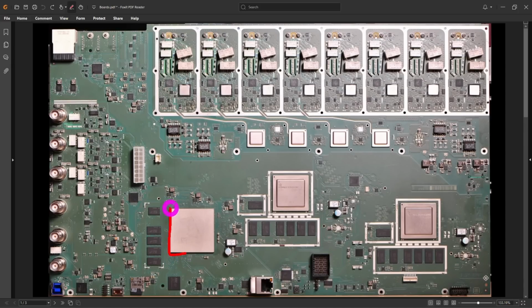Now, starting over here, we do have the AMD or Xilinx FPGA. This is an absolutely enormous SoC, a Zynq UltraScale+ FPGA. It does, of course, have quad ARM Cortex processors in it, which is probably where the application is running. It does have over 650,000 logic cells, which can work up to 1.3 gigahertz. It does also interface with its own memory, where probably the firmware is running. 512 IOs. Yeah, it's pretty big, and it's not cheap. Individually, over $8,000 each.